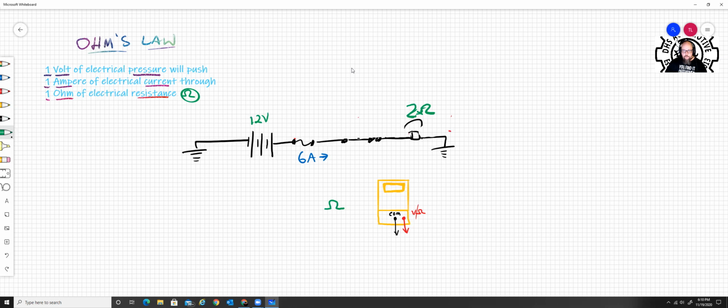Okay, so bottom line, if you start seeing dashes in the meter, where it's indicating I don't see anything, just click up through the ranges. You should have a 200 range, a 2000 range, 2 kilo ohms, 2K ohms, okay? You should have a 20,000 range. You should have 2 mega ohms or 2 million ohms. And then it goes on up. The same goes for the voltage ranges as well, although you're not going to be measuring millions of volts anywhere. If you applied that to something where you touched it, you'd cook yourself, okay?